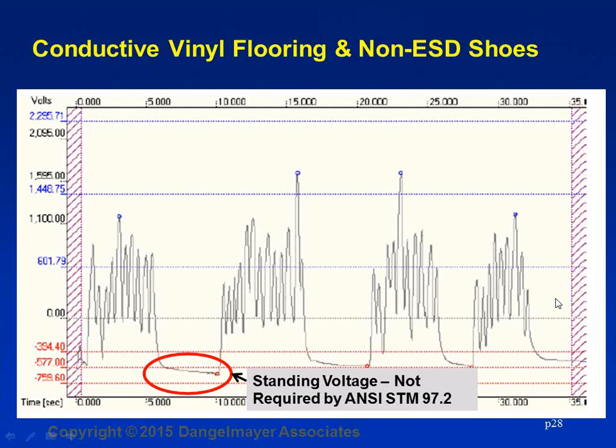Which is a good point, that it's important to select what you're going to use and try to standardize on it as much as possible so you don't have quite that many variables that you have to manage in your ESD control program. And we often refer to ESD shoes because most people know how to put their shoes on properly. There's a lot less training involved, even though heel straps or heel grounders seem like a more cost-effective solution in the long run. ESD-controlled footwear may be more economical, so we're mentioning that for you.